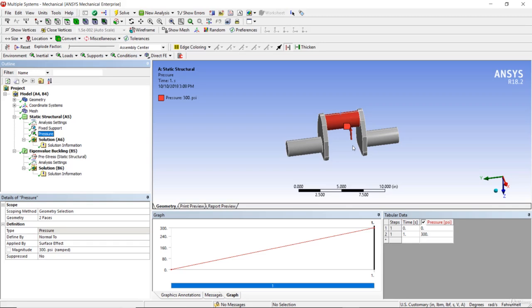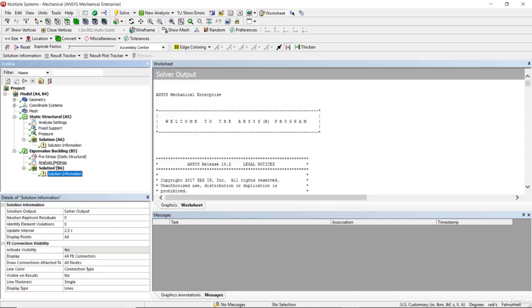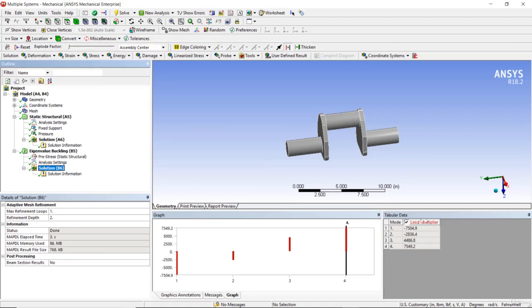So what happens is, it is up to the CAE engineer to define whether this particular buckling factor is going to be useful or not. So for example, in our case, let us say the load is always applied only in this particular direction and I don't have any change in the load direction, then I can just ignore these 2 buckling factors or load multipliers, and I can directly go to this particular mode and I can see whether it is going to buckle or not.